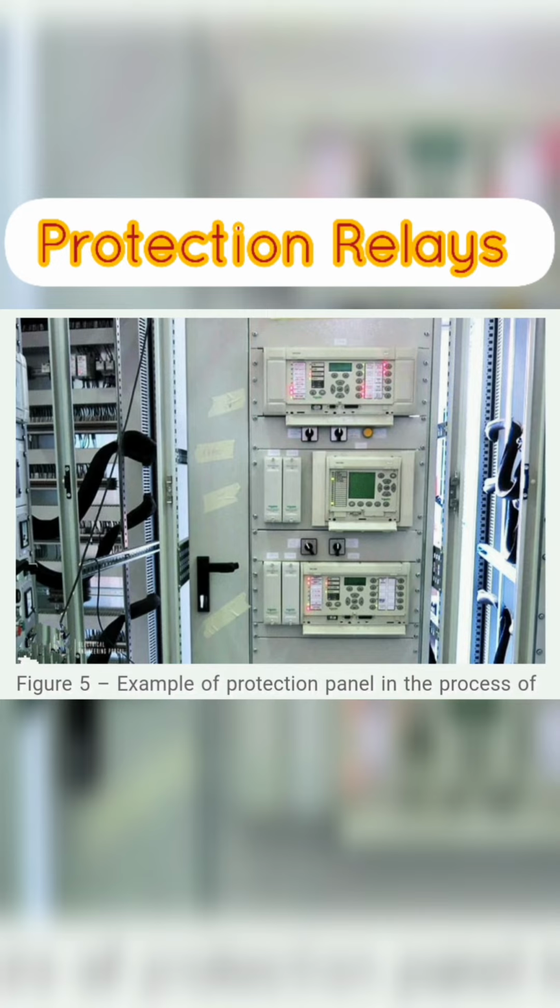The relaying equipment is aided in this task by circuit breakers that are capable of disconnecting the faulty element when they are called upon to do so by the relaying equipment. They must also withstand closing in on such a short circuit and then interrupting it according to certain prescribed standards. Fusing is employed where protective relays and circuit breakers are not economically justifiable.